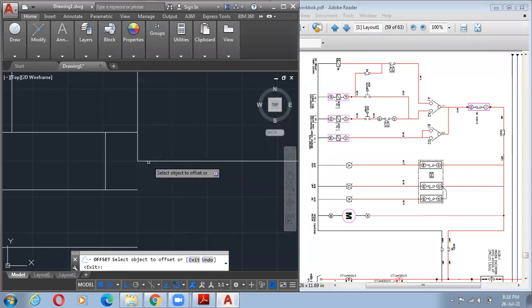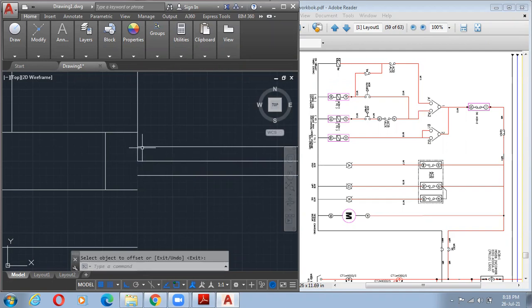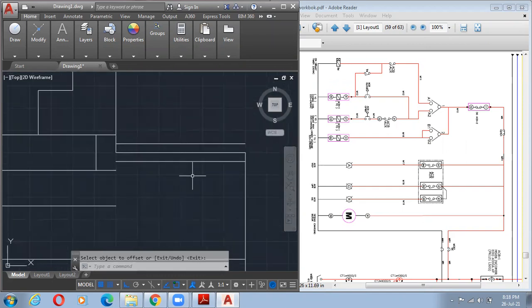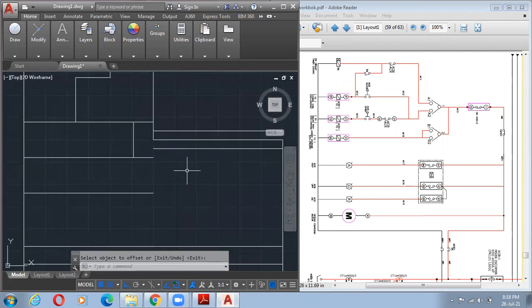That's enough. Select this and make it 5. Select this and change to 5. Okay, again enter. Here see, it will come up to here. Okay, so we can trim it. Choosing the trimming symbol will be an advantage for us, rather than always making it manually. Offset will be preferable.